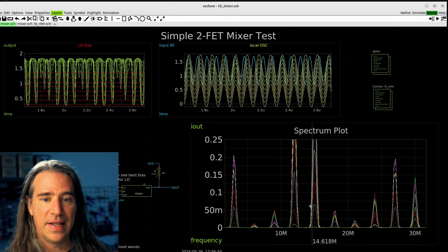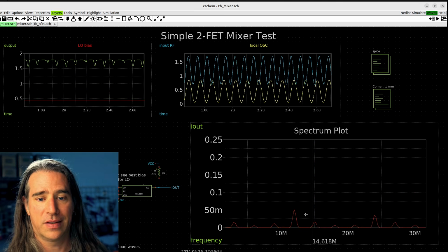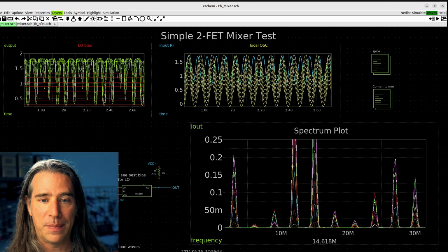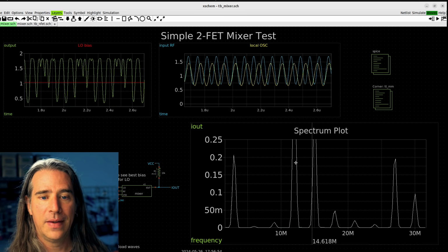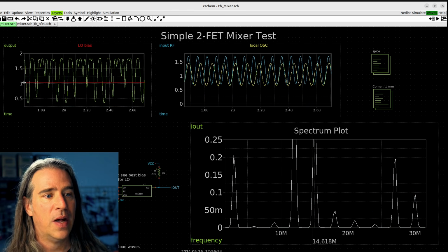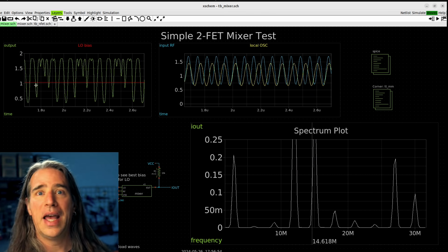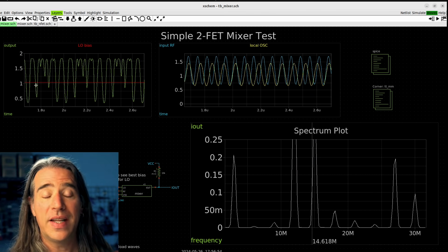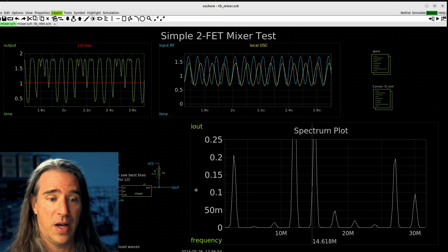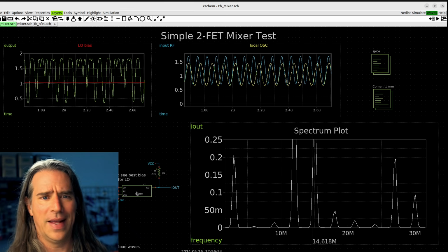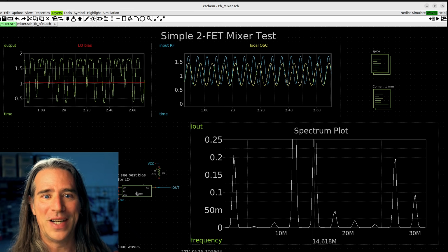Pretty cool. What you can tell is that with a low bias, it sucks terribly. But up here, yeah, that's pretty good. So a bias of about 1 volt, and we're golden. That's what the test bench is for. You get to know your circuit a little. You know that it works, and everything is beautiful. And these graphs make it really nice to look at too.